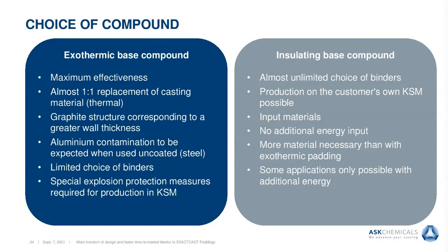Then inside the exothermic mix, you have some reactive elements, because you need them for the exothermic reaction, and you should consider that they can also react with your melt, but you can avoid or limit that by using a coating here.